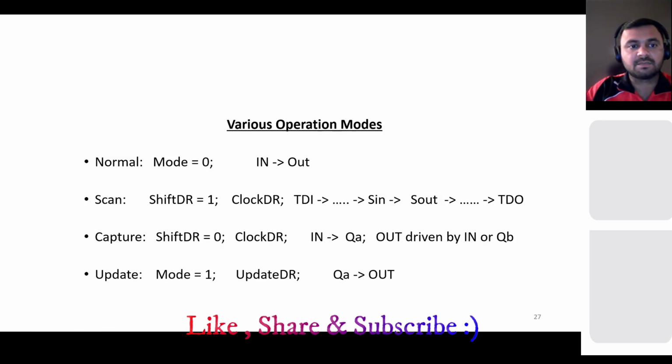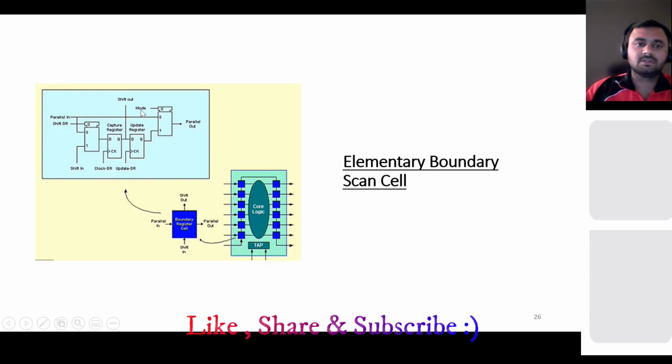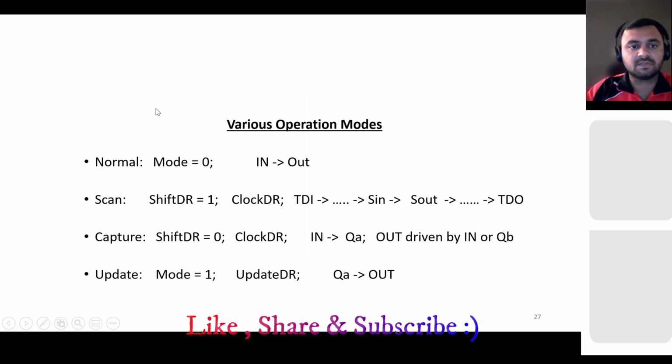So we have 4 basic operations: normal, scan, capture, and update. So for the normal mode, if mode is 0, your parallel out will be the parallel in. So you can directly pass this parallel input to the parallel output by using this mode 0. So the first one is the normal mode, like functional mode.